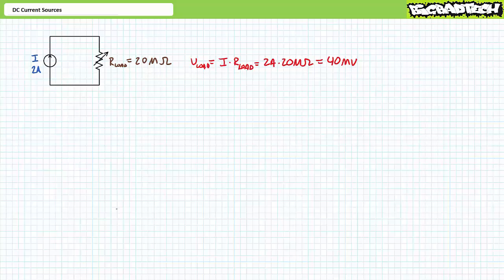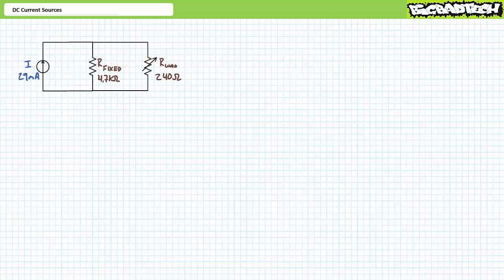40 megavolts. Can you see the difficulty in purchasing a current source that will push 2 amps through a circuit regardless of applied load? Not going to happen. However, if we suspend our disbelief in physics, sure, it could happen, and an Ohm's law analysis gives us the necessary proof it could. The current divider rule is an especially handy technique when performing circuit analysis using current sources.